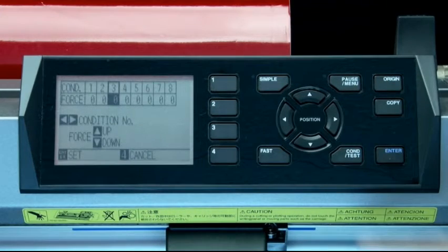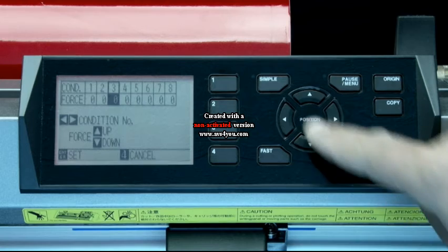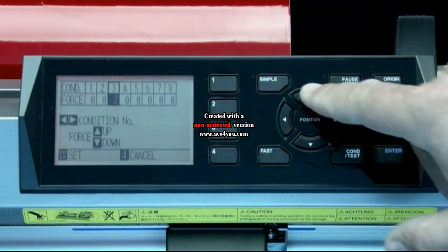When cutting thicker media, additional time is required for the cutter blade to penetrate the media fully, even when the necessary cutting force is applied. When this happens, it can leave an uncut section or sections. When the initial downforce is increased, it's added to the initial cutting force when the tool comes down to penetrate the material.